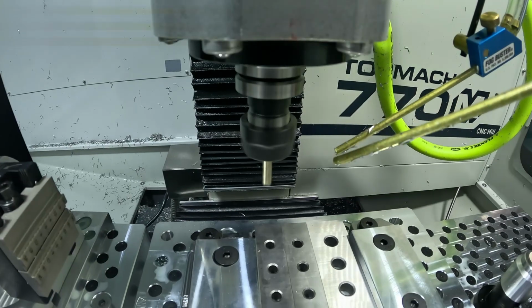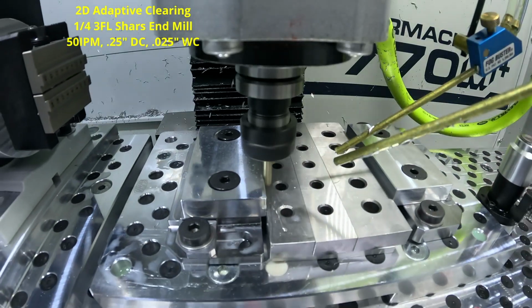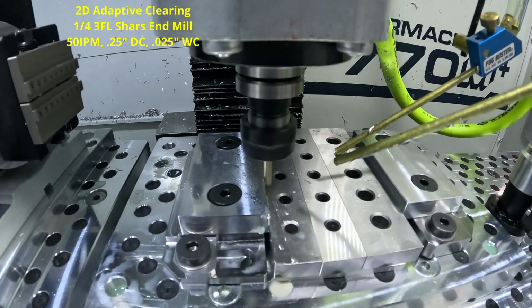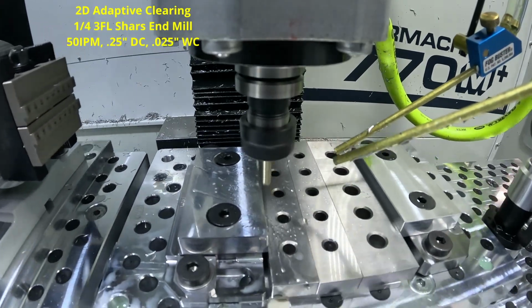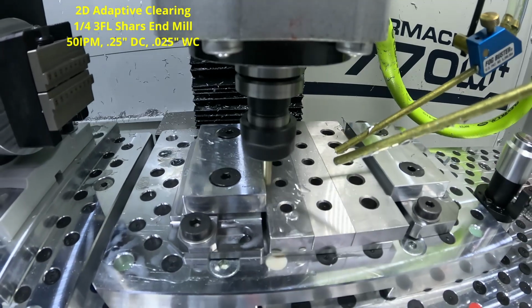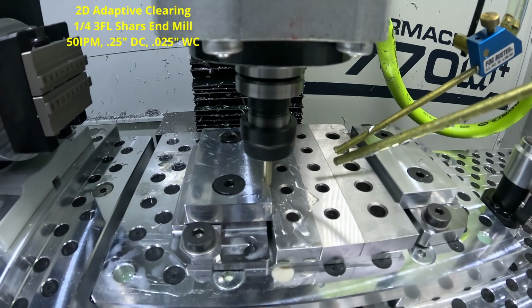Alright, so we begin making our soft jaws with our 2D adaptive clearing using a 1/4 inch, 3 flute Shars end mill, 50 inches per minute, 1/4 inch depth of cut, and 25 thousandths width of cut. I think I definitely could have pushed the feeds and speeds with this tool, so I'll keep that in mind next time. You notice I have the parallel stacked there to get my 3.5 inch jaw gap.